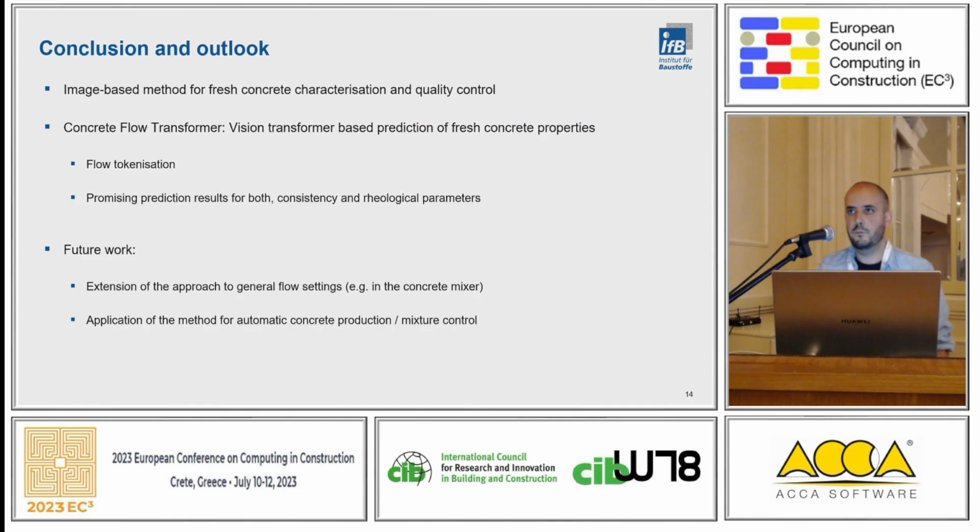So to conclude, we presented an image-based method for fresh concrete characterization and quality control, which is applicable on the construction site, and which has the advantage that not only a batch-based quality performance is done, but in theory, every liter of the concrete brought to the construction site could be tested. And we presented the concrete flow transformer, especially our proposal of flow tokenization, and achieved promising prediction results for both the consistency and also the rheological parameters.